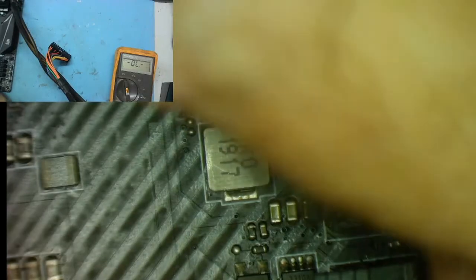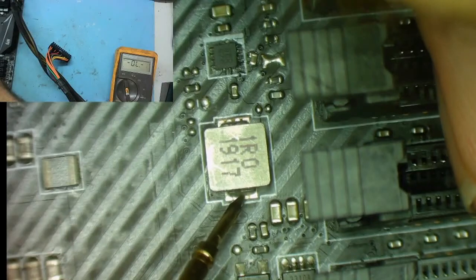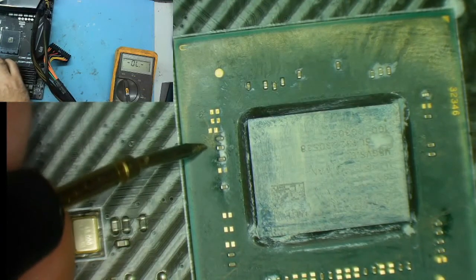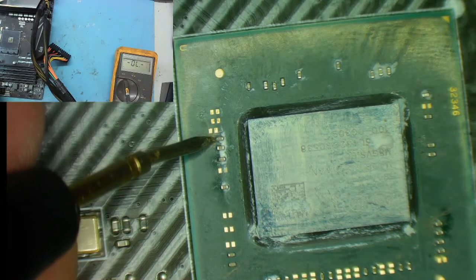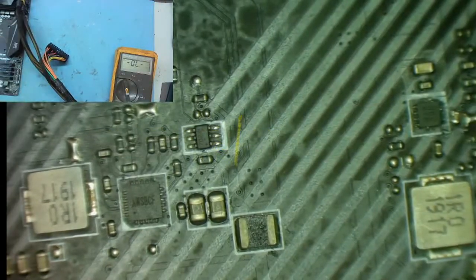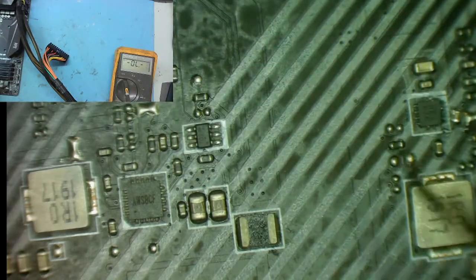Found it. That comes from this one over here, onto that capacitor. And to prove I'm right, let's go back over here. No skullduggery here. This is the capacitor where we saw the 0.7, and I'm on that coil. I'll keep the meter probe on it without moving it. I'm on this coil over here. So that's giving you the 0.7, that's right.